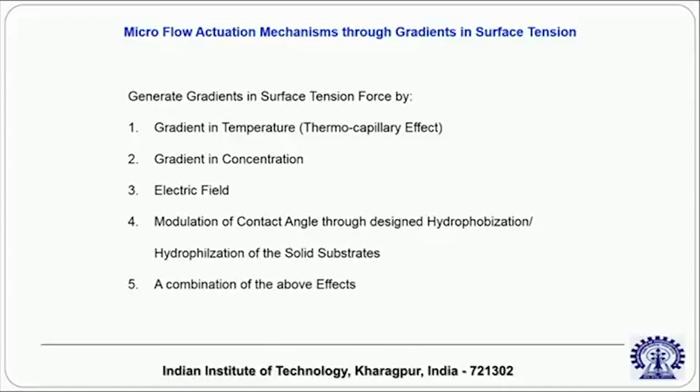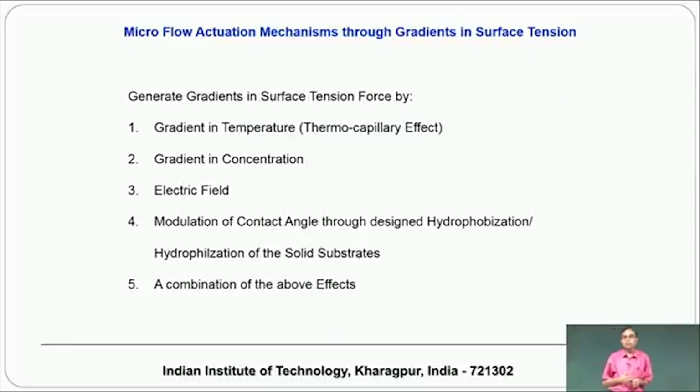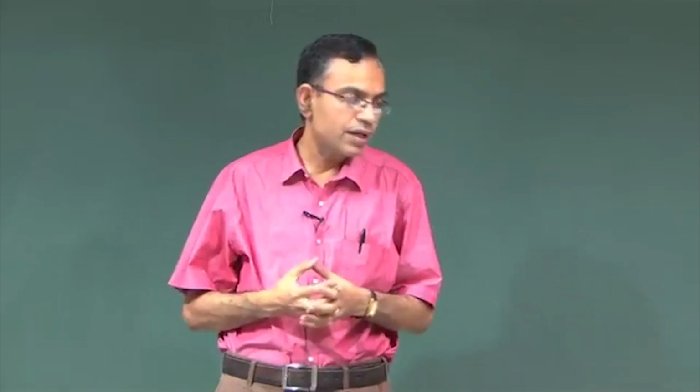You can generate gradients in surface tension force by generating gradients in temperature, gradients in concentration, you can create an electric field, you can modulate the contact angle by making a surface hydrophobic or hydrophilic.